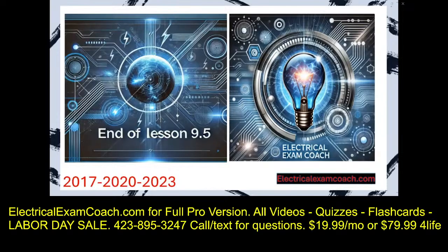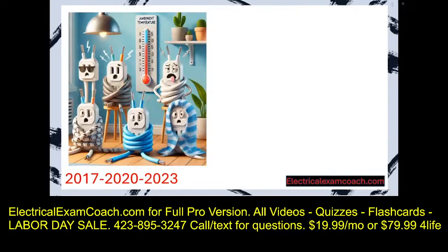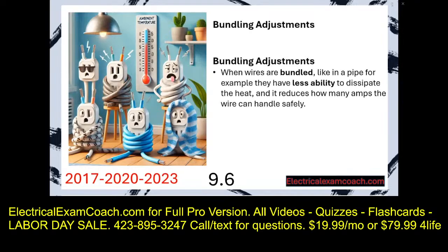Let's get to it. Hey everyone, welcome back. I am the Electrical Code Coach from electricalexamcoach.com, and this is lesson 9.6 in our video series. In our previous lesson, we learned all about bundling adjustments and how to derate them when wires are bundled inside of a pipe, cable, or raceway. In this lesson, we're going to be learning about ambient temperature corrections. It's very similar. We just pulled from a different table, but it's the same style demand factor process that we've been doing this entire program.